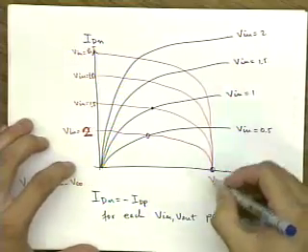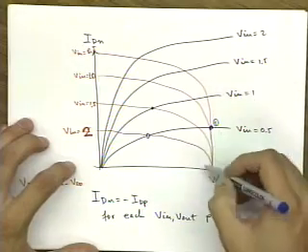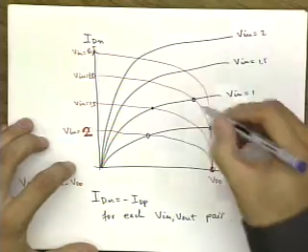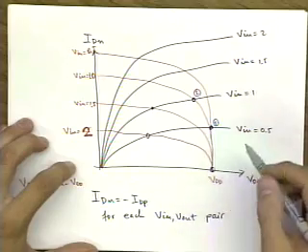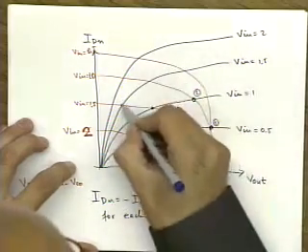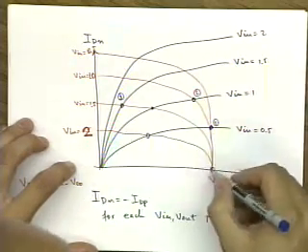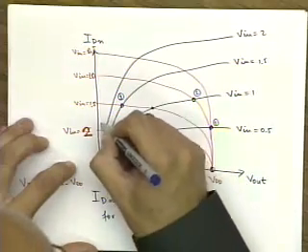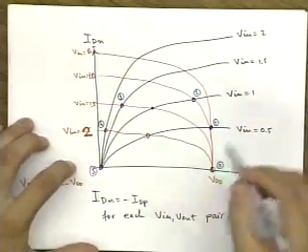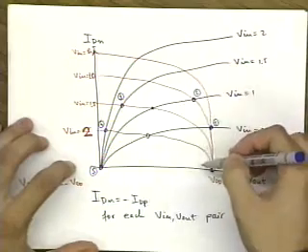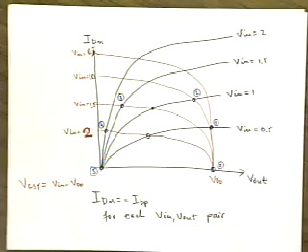So we take V in is equal to 0.5, we end up here. So that's point number 1. Then we have V in is equal to 1, we move over here to point number 2. V in is equal to 1.5, then we are already here. And then we have V in is equal to 2, then we are over here. And if we started, this is 0, and this is 5. And now using these values, we can plot the voltage transfer characteristic. Can you write bigger? Bigger font? Okay, yes, sure.